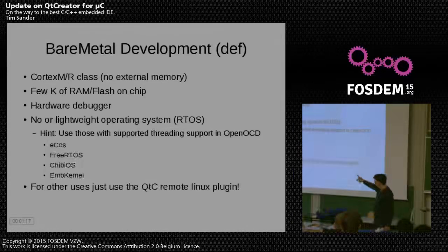So currently the list is eCos, FreeRTOS, ChibiOS, or the embKernel. And if you're developing on embedded Linux stuff or so, you're not going to use the BareMetal plugin, because you can use remote Linux debugging, which is also very well supported in QtCreator, but I'm not going to talk about that here. It's been working for several years now, so that's nothing new.